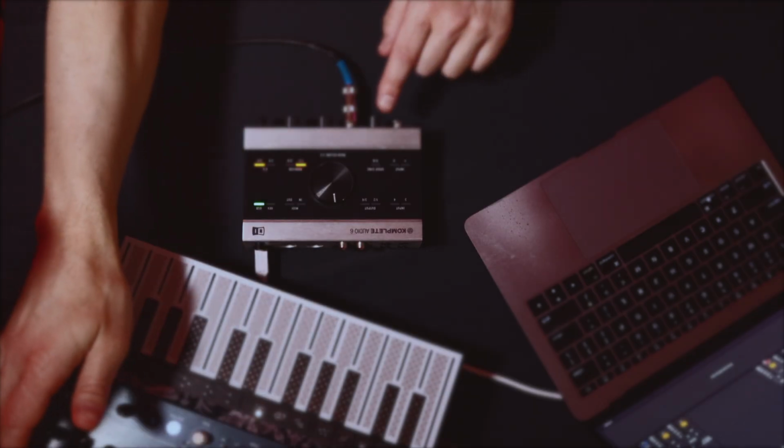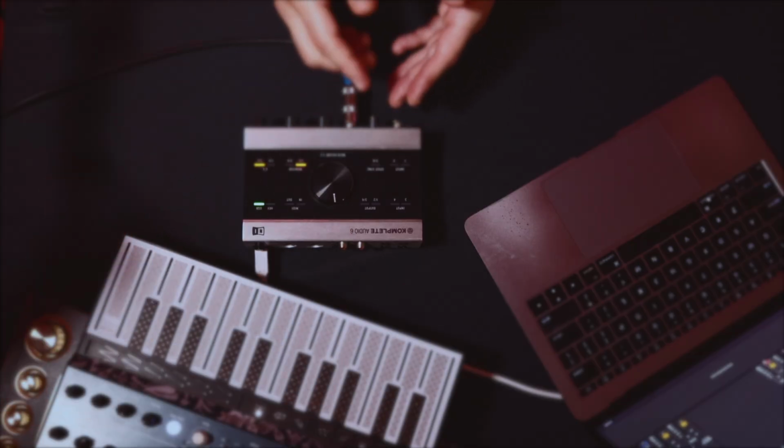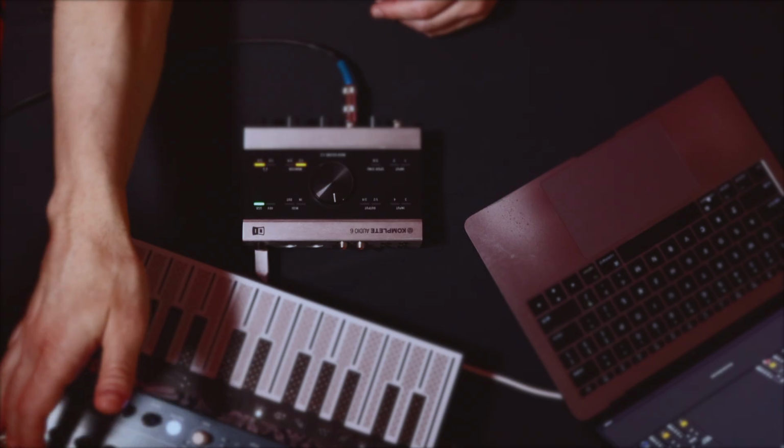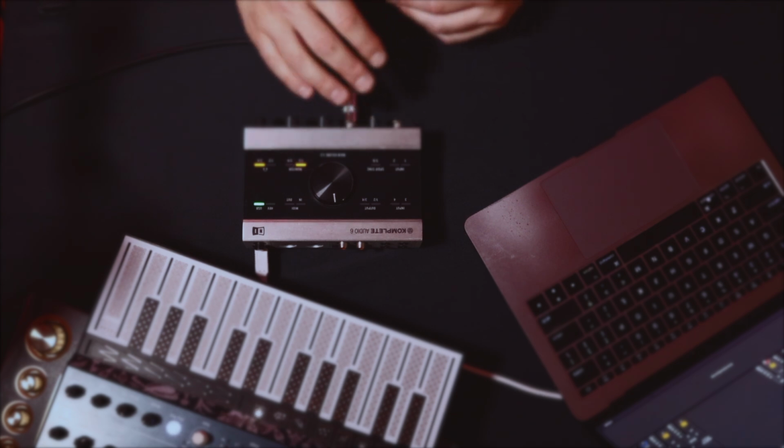So unlike most microphones that don't have a volume control on them except for, say, a USB podcasting mic, I now have two places where I can control the gain or the volume. I have the output of the synth and I have the input on the audio interface. So you want to have this set up in such a way that you're not sending it in really hot and clipping into here and then just turning this preamp down, because then you're going to get a distorted signal. In the reverse, I also don't want to have this turned really far down and then turn this all the way up. Otherwise, I'm going to be amplifying a lot of noise.